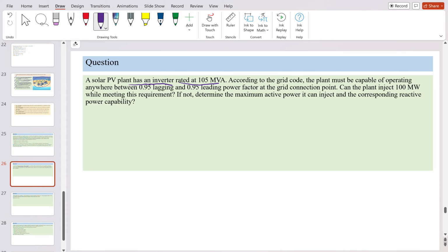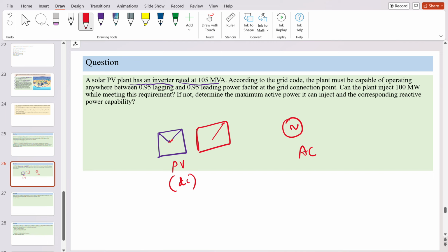It is like this. So you have a PV plant, and it generates DC. For the conversion, because the grid requires AC, in between you mainly keep a DC to DC converter to uplift the voltage which is there at a DC link capacitor, and then you have a DC to AC converter.